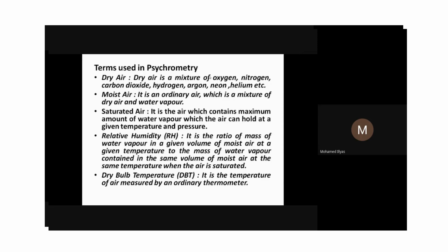The refrigerant coming out from the evaporator should be heated. That is our concept: when it is heated it will become vapor. The refrigerant coming out from the condenser should be further cooled so that there is no vapor and it is completely in liquid form. So both are combined in more and more heat transfer.